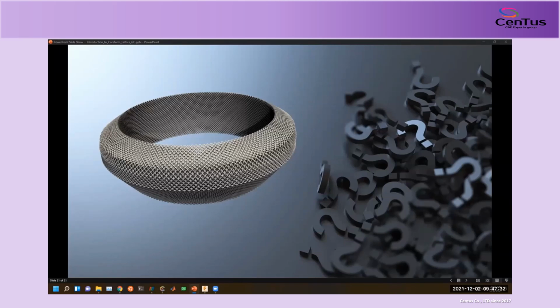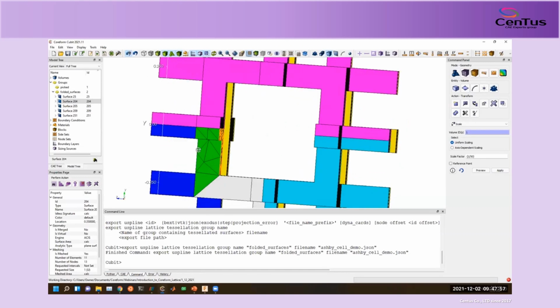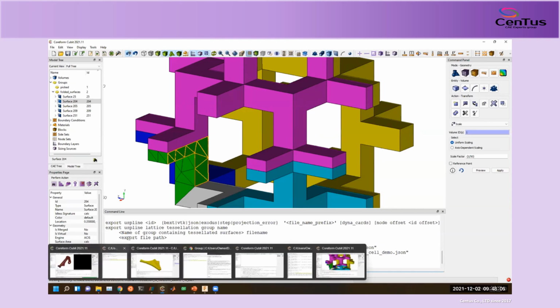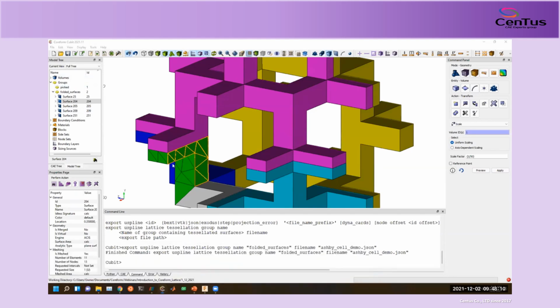We got a question from Ron. Will you be able to use the lattice as a geometry that could then be meshed and exported to an FEA solver like Abaqus? So at least right now, the lattices that we can export are exported as triangle tessellations. And they'll inherit that tessellation from this tessellation you see here. Now, once you have, say, one of these solids, let me see if I can actually import, maybe a demonstration here.